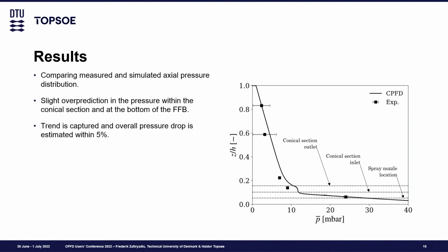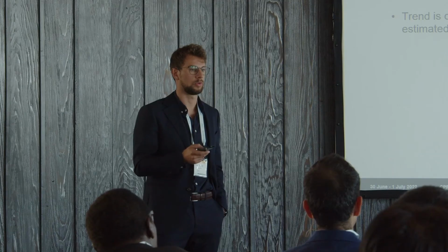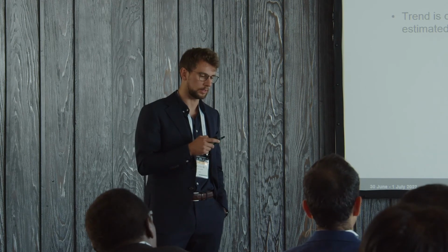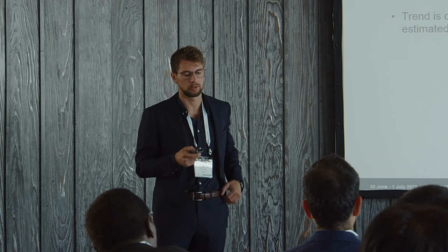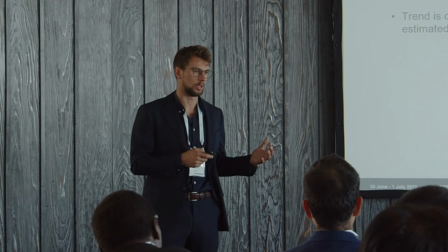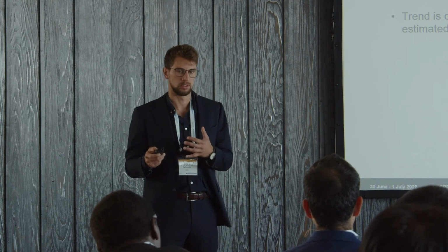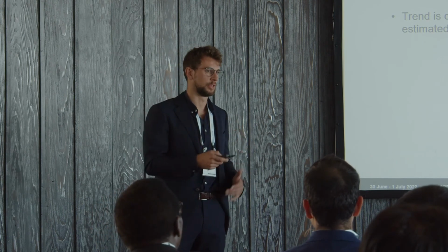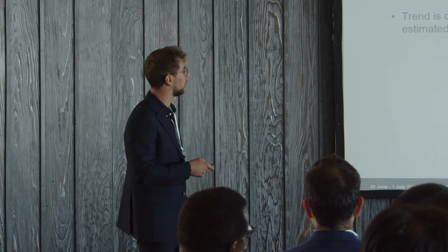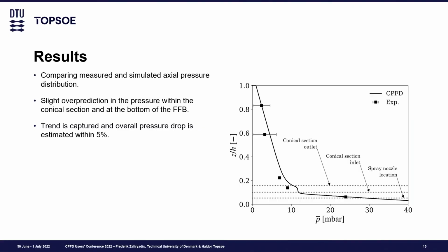So as I said before, we do have measurements of some stuff. We can measure yields, we can measure temperature and pressure across the height of the riser, but the amount of data that we can get from the setup is quite limited. Also, due to proprietary reasons, I'm not able to show most of the actual interesting results. But I am allowed to show this here, which basically goes to say that in terms of the hydrodynamics of the system, we're capturing the overall pressure drop and pressure distribution quite well, which is also what we saw from the cold flow simulation. So quite happy that it seems to work both on cold flow and hot flow.